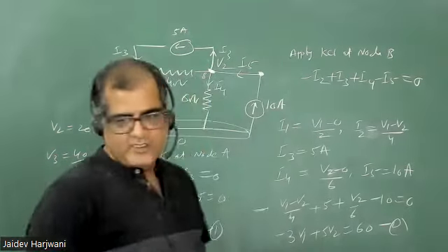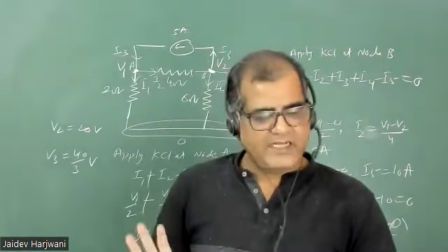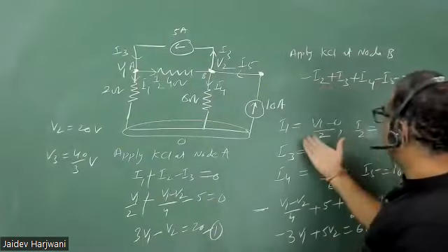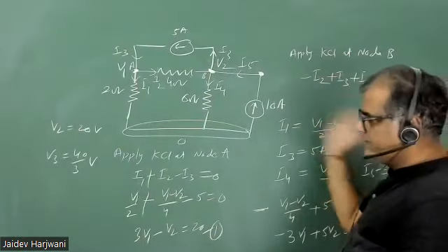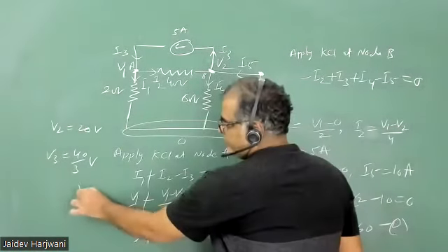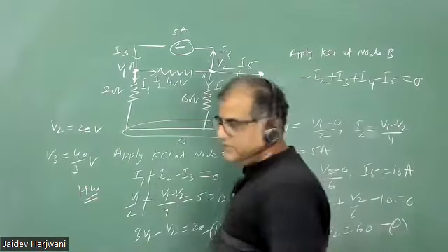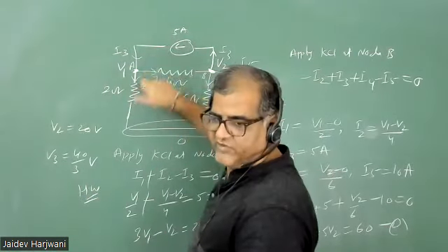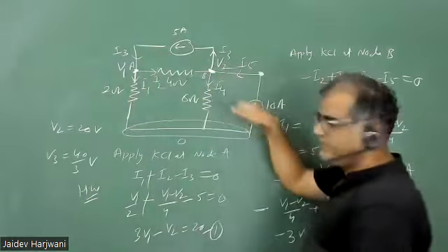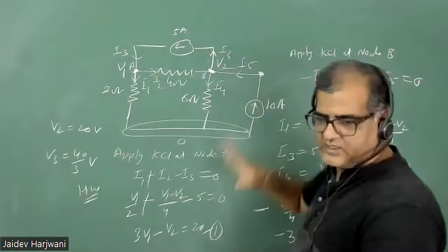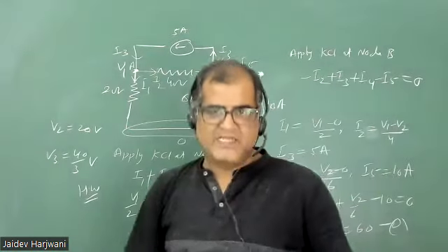Okay, so this technique is very simple. Even if many things are unknown, now you know all the voltages, you can find all the branch currents. So that is your homework, calculating branch currents. And then you can check, 5 coming, so how many going here, how much going here. You can verify also. Similarly here you can also verify. How much coming here, how much going and how much coming here. So you have to calculate I1, I2 branch currents also.